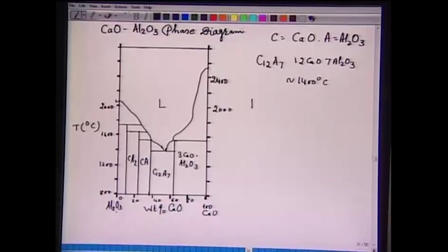Good, we have got an element. What are the problems? The problems with calcium addition are as follows. Calcium has a density of 1.55 gram per centimeter cube. What does it mean? It is very difficult to introduce into the melt, which has a density of 7 gram per centimeter cube. It has a boiling point of 1492 degrees Celsius. What does it mean? At the steel making temperature, which is 1600, it is in the vapor form, and vapor is highly reactive.